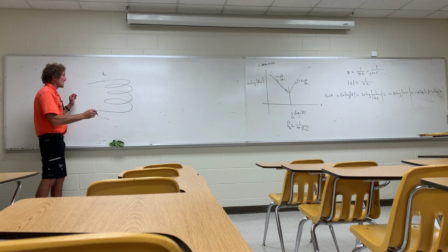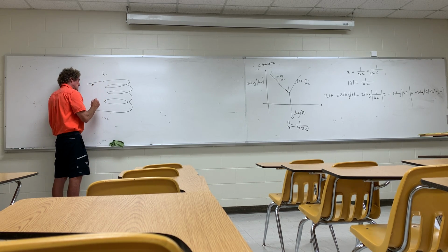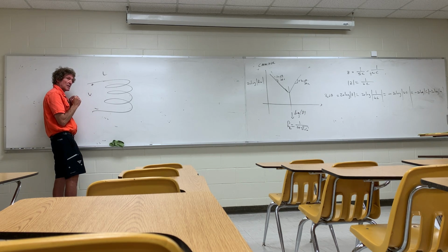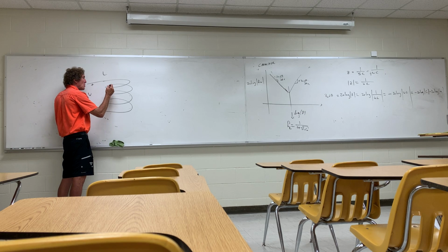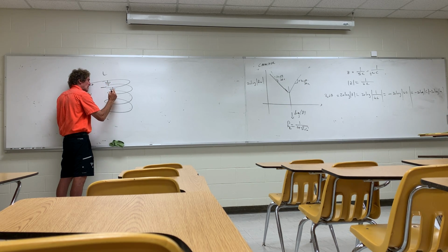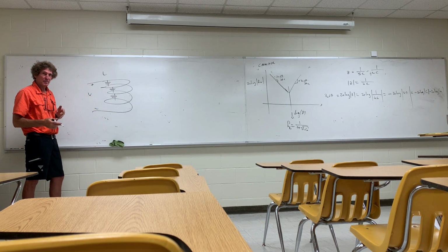One thing you have to realize is that there's a voltage difference V from top to bottom, and it's an AC voltage. That means there is a small but measurable voltage difference between this point and this point, or there is an effective capacitor per winding. There's a capacitance per winding. Think about that just for a second.